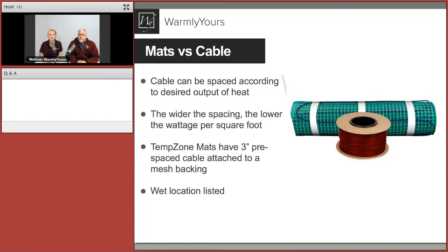So we have a question. Laminate will not warrant over electric floor heating. Only water-based systems are recommended. There are laminate companies that will void their warranties if you put electric floor heating over their products. We are working on that issue with laminate companies. What you will find for many of them is that they will allow it if the heating element is embedded. And so we'll talk about that. Actually, it might be the next slide or two.